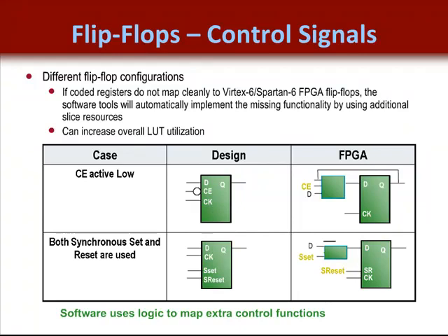Now, I would also like to ask you another question that is not shown in this slide. What if an asynchronous set was used in the lower example rather than a synchronous set? Well, the answer is that since the asynchronous sets and resets get access to the control port before synchronous set and reset control signals do, the asynchronous set would be connected to the flip-flop rather than the synchronous reset as shown in the diagram. This would then force the synthesis tool to map the synchronous reset to the LUT input.